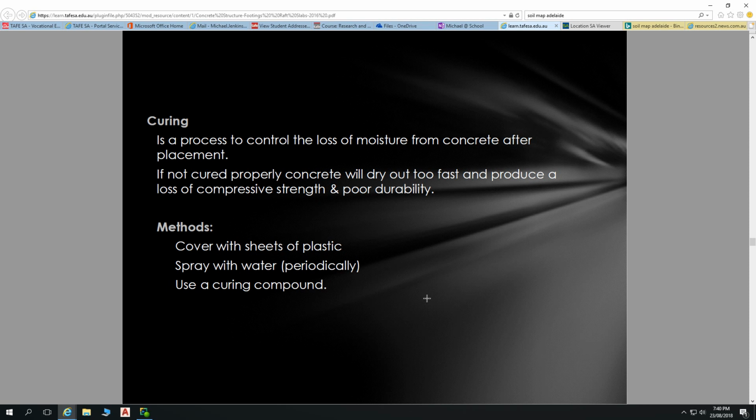What you don't want to be doing is spraying it with water when the concrete is still plastic, when it's still really soft. However, you probably noticed on the footpaths here near the car park, anybody seen those during the day, that it's actually a rough finish. On your way out to the car, have a look at the concrete there. It's probably going to be a bit too dark to really see it, but it's really quite grippy. What they've done there is they've laid the concrete, and then when that concrete has gone off fairly well but hasn't hardened, they've gone over the top with a high pressure cleaner to blast away a lot of the fine aggregates and give a rough surface to that concrete.